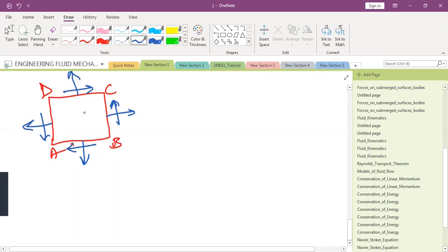So it has both normal and shear stresses. So if I want to find out stress at point P, this is what I have actually assumed around point P, this ABCD. Now if I ask you, I want to find out stress at point P on this vertical line, on a plane which is this AB plane, or say this is the 1-2 plane.